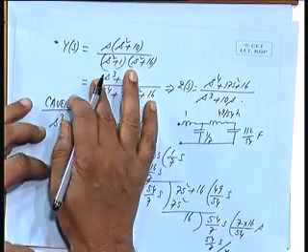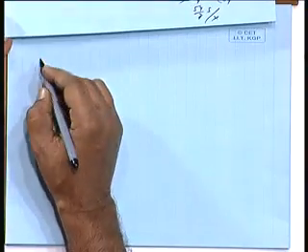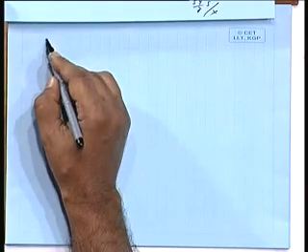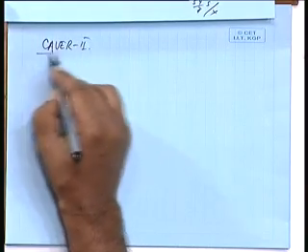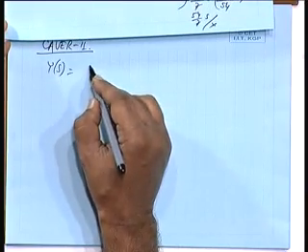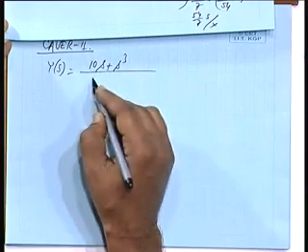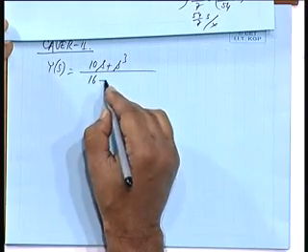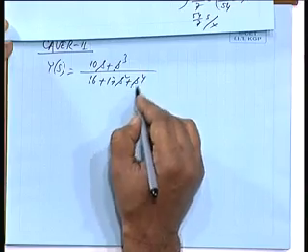If you reverse the order and start the division, Foster 2, if I am asked to realize this by Foster 2, Y(s) was (10s plus s cubed) divided by (16 plus 17s squared plus s to the power 4).